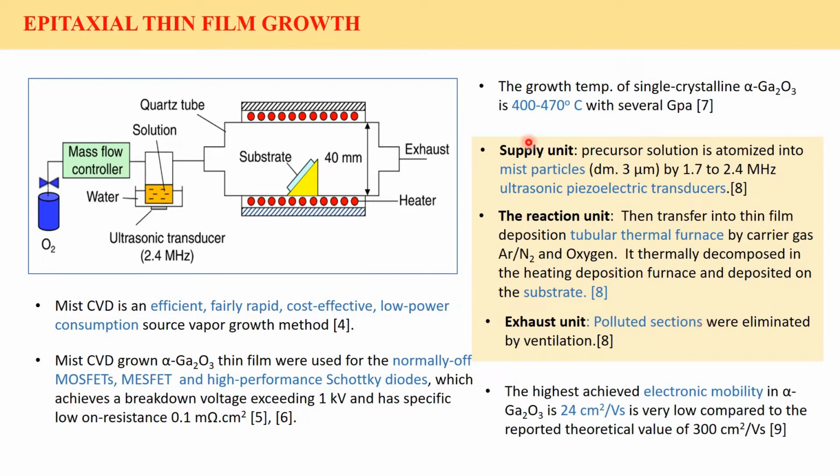So in that we use a sapphire substrate. Why do we use it? Because after several studies among materials, we realized the sapphire substrate's lattice constant is very close to the gallium oxide lattice constant. Because for a good crystalline alpha gallium oxide, we need an ideal substrate. So sapphire is a very good substrate to deposit alpha gallium oxide.